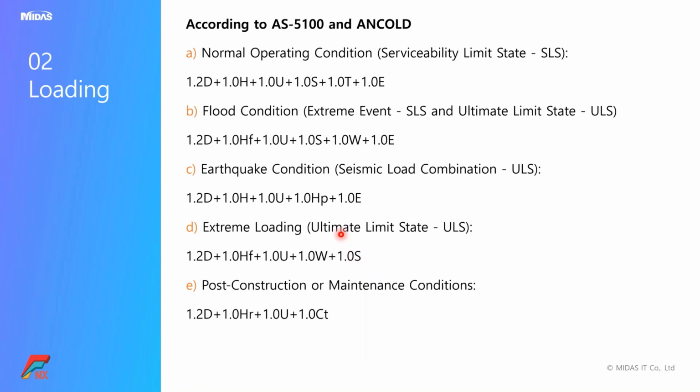And for reference, we have similar load combinations present in AS 5100 as well as the ANCOLD guidelines. So for those who are dealing with Australian projects, you need to consider these load combinations according to the ANCOLD guidelines. There is a very subtle difference between the Indian standard and Australian standard load combinations. In the Indian standard, the loads are applied as they are, but in the assessment, like for stability checks as well as factor of safety checks,